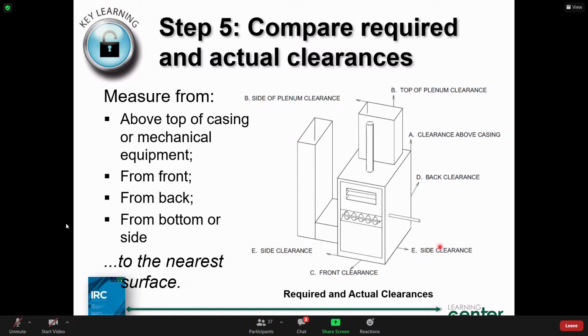So, in reality, everything burns. You know, it's just the time that it's going to take to burn. That's what we're after. Okay, so we're just looking at things that are classified as combustible materials. So in other words, we're looking for clearances here, right, Francisco? We don't want the furnace to be too close to a combustible material to give off maybe radiation or, by convection, a heating effect on those materials to maybe cause something to combust, maybe get too hot, right?